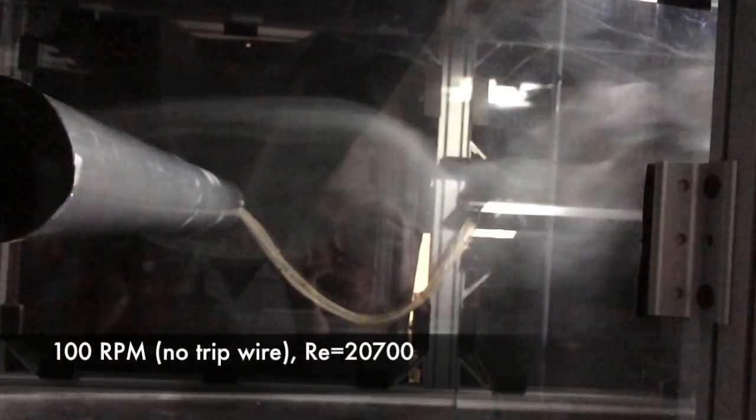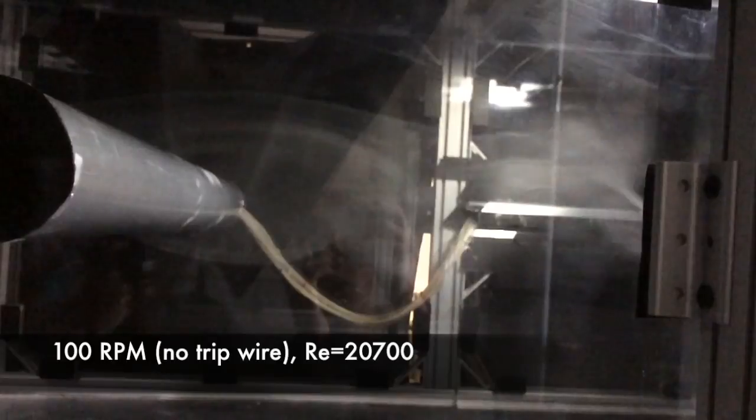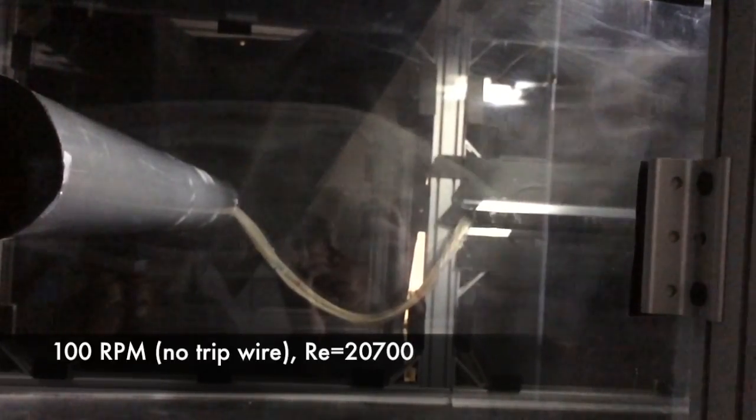The frequency of this shedding is directly proportional to the Reynolds number of the flow and can cause undamped oscillation if it matches the fundamental frequency of the object in the flow. To prevent such unwanted oscillation of the cylinder, we kept the wind tunnel's free stream velocity from exceeding 30 meters per second.